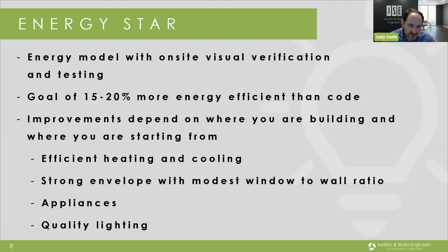Okay, I got one more question. You mentioned appliances here, and one of the questions I'm reading is, do all the appliances have to be Energy Star to meet the Energy Star certification? Oh, that is a great question, and one we get frequently. In previous versions of Energy Star, it was mandatory that the appliances within your dwelling units were Energy Star certified. Under the new guidelines, you do not have to have them Energy Star certified, but it does help for compliance within the energy model.